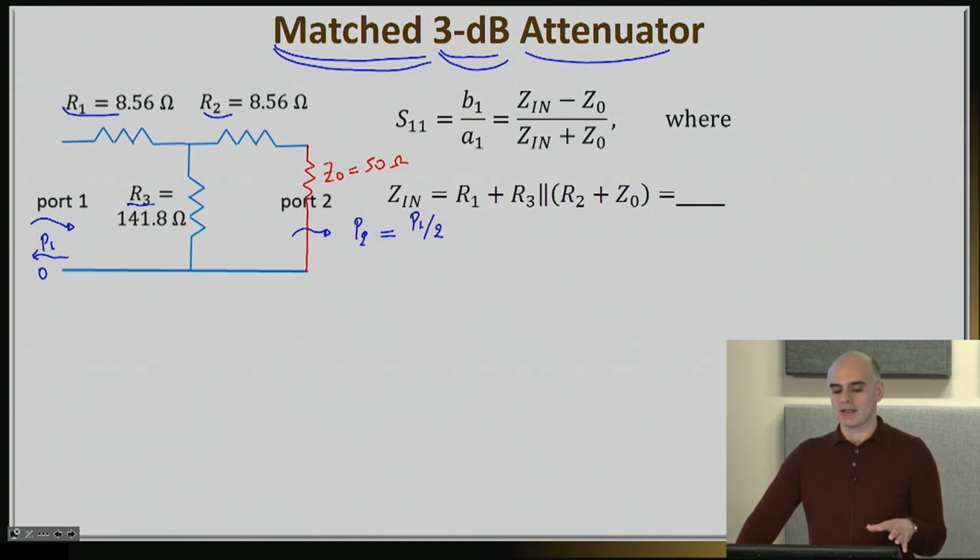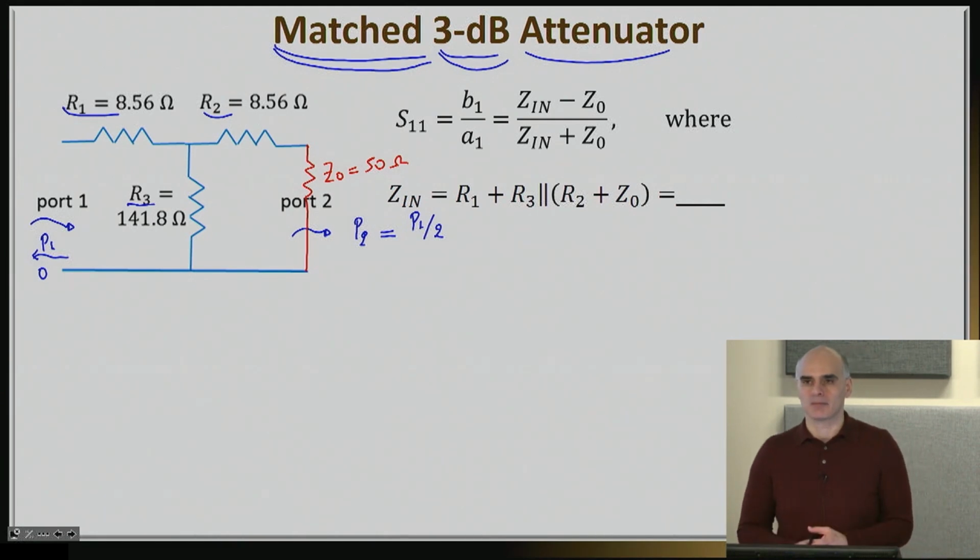The good thing is that, as we will see later on, once you do know the S parameters for one reference impedance, let's say in this case 50 ohms, it's very simple to rescale them to a different reference impedance. And so you shouldn't be afraid to choose the impedance, even if later on the same network is utilized in a different system impedance. You can simply rescale the S parameters.